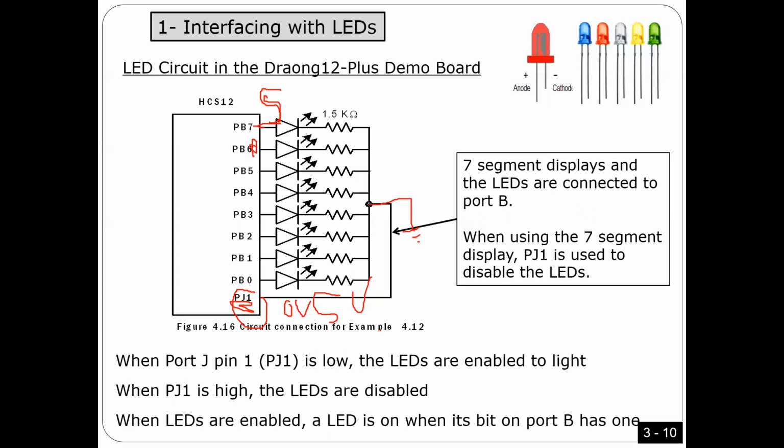That's why, for every device here, they have an enable. And on this enable, if you put logic 1 or 5 volts, you actually turn this one off. Same thing here. You put 5 volts, this one is off. 5 volts, this one is off. 5 volts, this one is off. 0 volts, this one is on. That's how you make only one of them on.